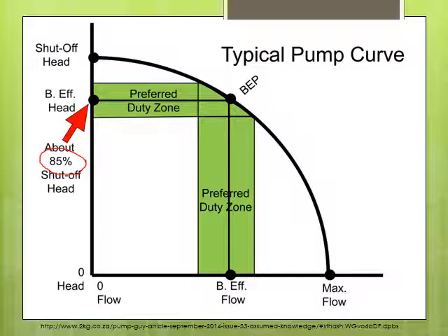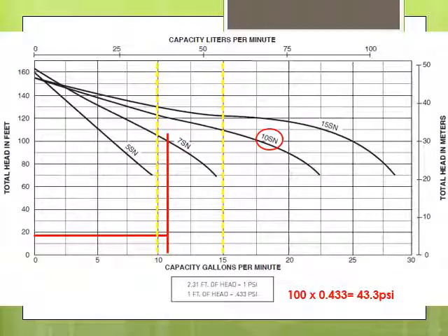And so that last pump we saw, which was at 10.1, was basically at 100%, where the next pump, which was 15, puts us at around 75%, which is okay. That's maybe a little bit big, but it's not like they've got an infinite selection of pumps. So we know which pump we need to buy. There it is, 10SN, this one here. That's the one we want to buy.